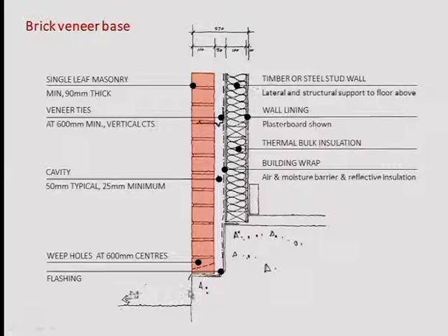On the outer side, there is the brick veneer. So the brick veneer is not a structural element, it's just meant to self-support the wall. So it's self-supporting, all right? And it is connected to the structural elements with these ties. So you see here there are ties that at the same time connect the wall and make sure that it's laterally stable, but also they make sure that there is a joint, because these two layers, these two lifts, can behave in different ways.